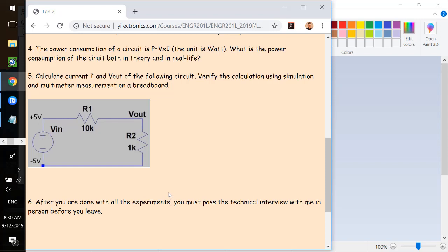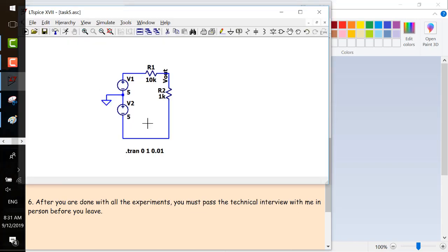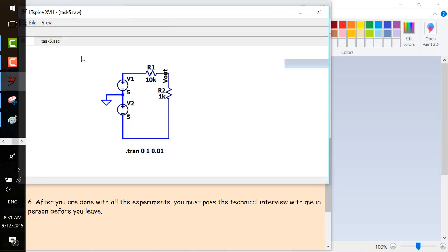So from -5, you increase by 1 volt, and you reach VL. Which means VL will be -5 plus 1. It's not 1, but close to 1. It's going to be something around -4 volts. So VL will be something around -4. So you can do a test. Build up the circuit like this in LTSpice, do a simulation. Let's run it, let's see.